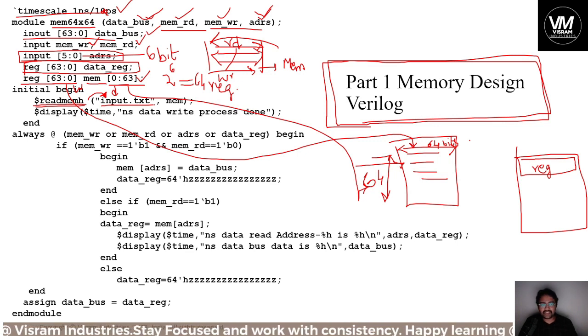Usually in larger complicated designs it is automated, but you have to give the file location on your machine where the file is actually present. So if you are using the Xilinx EDA tool and you are stuck at this point, try giving the location of the file, input.txt and mem.